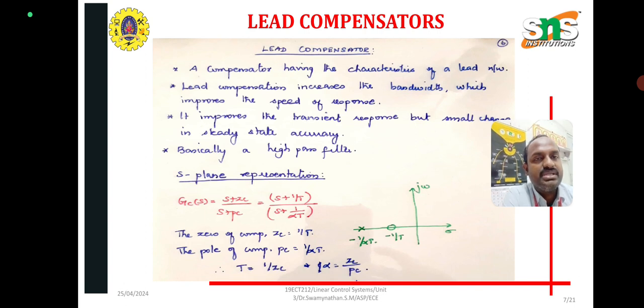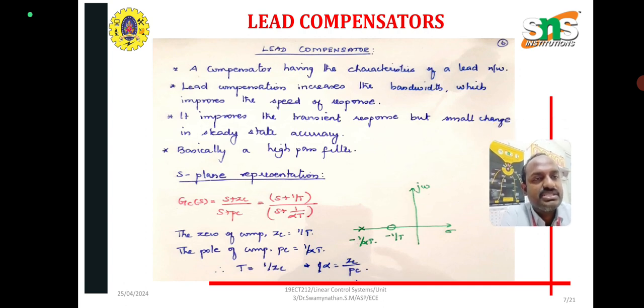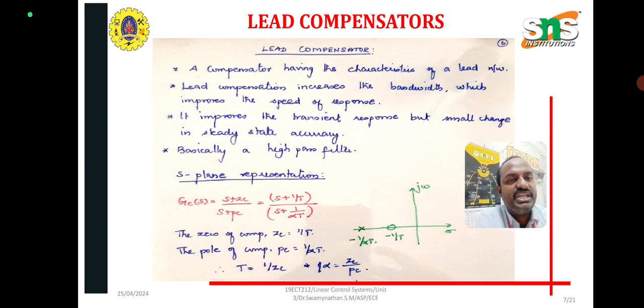The lead compensator is a compensation having the characteristics of a lead function. The lead compensation increases the bandwidth, which improves the speed of the response. It improves the transient response, with only a small change in steady state accuracy, and it behaves like a high pass filter. The S-plane representation: s plus zc, that is s plus 1 by T, for the zero, and s plus pc, that is s plus 1 by alpha T, for the pole. Just remember, transfer function is equal to zeros divided by poles.